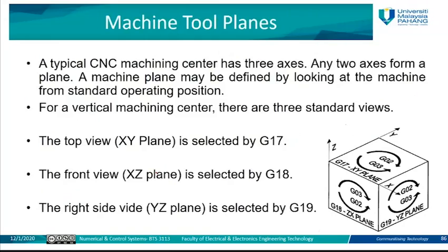This is the blend that we mentioned before. The convention for clockwise and counterclockwise is defined according to the plane. If you are going to use G17, the XY plane, this is the clockwise and this is the counterclockwise. The XY plane means the top view of the machine table. If you work on the XZ or ZX plane, this will be the counterclockwise and this will be the clockwise.